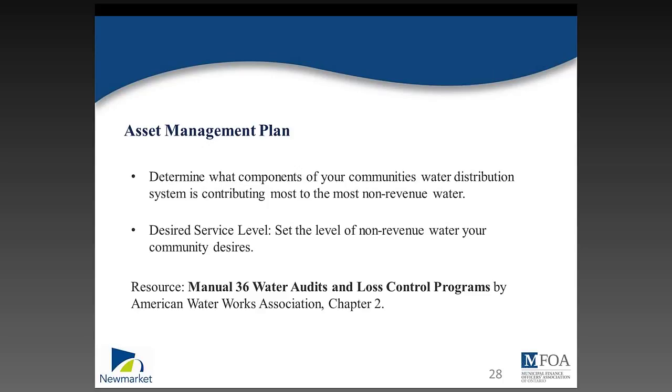You might want to say zero non-revenue water is the target, but that would be an impossible and extremely expensive pursuit. Discuss with your colleagues what level of non-revenue water might be achievable in the next decade. As a benchmark, in Canada, the average percent of water that is lost through flushing and leaks was 13.3%. This percent does not account for unbilled consumption. No data was found estimating the average total percent of non-revenue water.